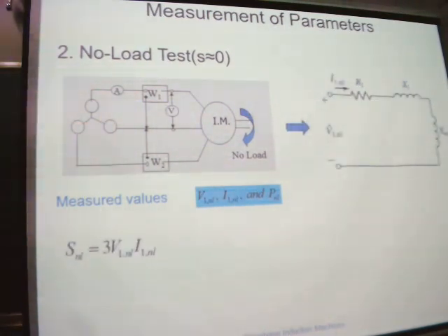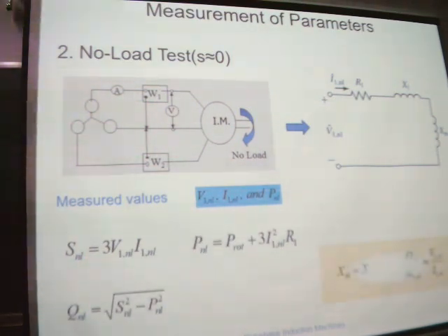And also, here, we usually apply a rated voltage at the stator terminals. We measure the voltage, current, power, and the rotational losses.